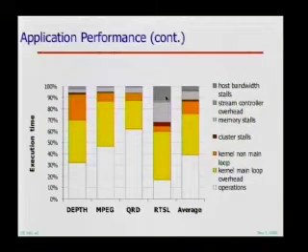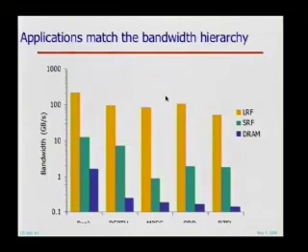So here we're able to get good performance across a range of applications. And one of the reasons we're able to do that is because the software was really able to take advantage of this tree-structured memory hierarchy and take advantage of the fact that referencing things from these register files that's sitting right next to the ALU is essentially free, in contrast to a big global multi-port register file on a conventional processor, which is not at all free. And referencing from your lane of the SRF is relatively inexpensive, and only rarely do you go out to memory.